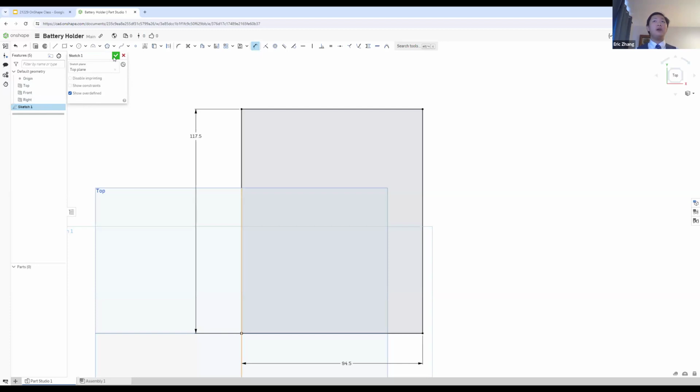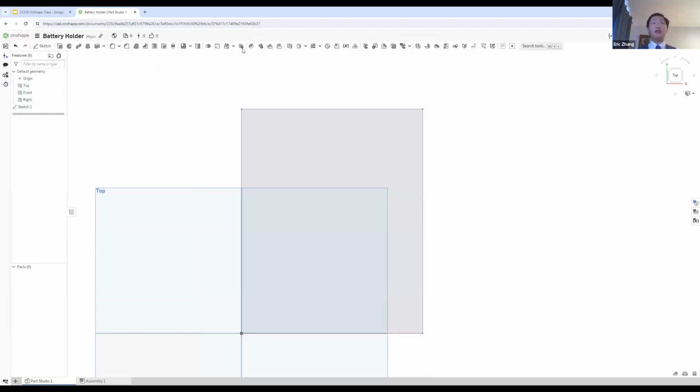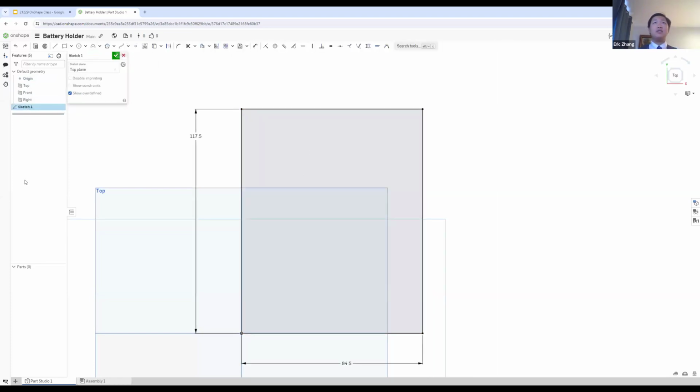If you manage to get out the sketch box format thing, you go to the top left corner and you click sketch. You click on the sketch, and thus you can re-enter the sketch that you've made. And how do you type the dimensions? I can't change it. Okay, so to answer your question, Darko, you can press D, which is this button over here, which is dimension. This will then allow you to click on one of the side lengths for the rectangle, and this will allow you to alter its dimensions.